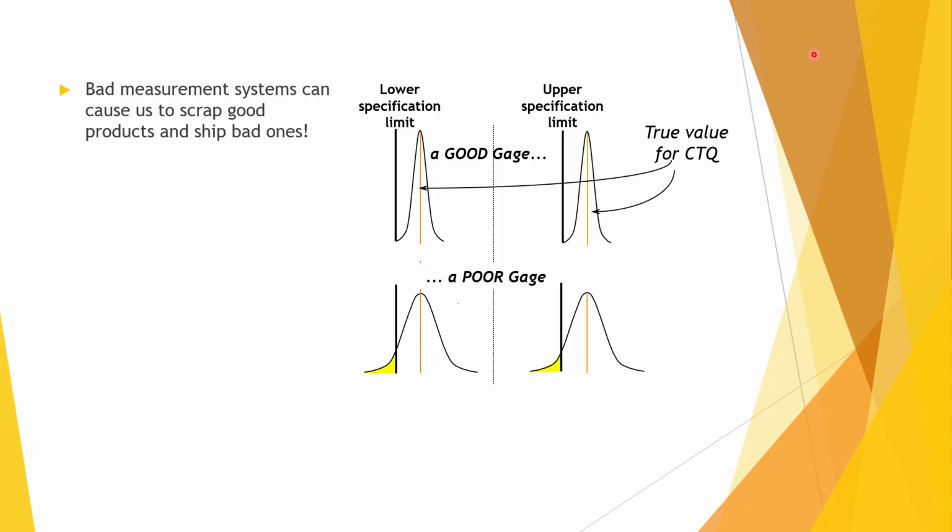Selecting the appropriate gauge will depend on the application, what you want to measure, and how you want to use the data. If you simply want to separate good parts from bad ones, then fixed size go/no-go gauges may provide all the information necessary. If you want more information on how good or bad a part is, for example, to assess capability, use gauges with numeric readouts.